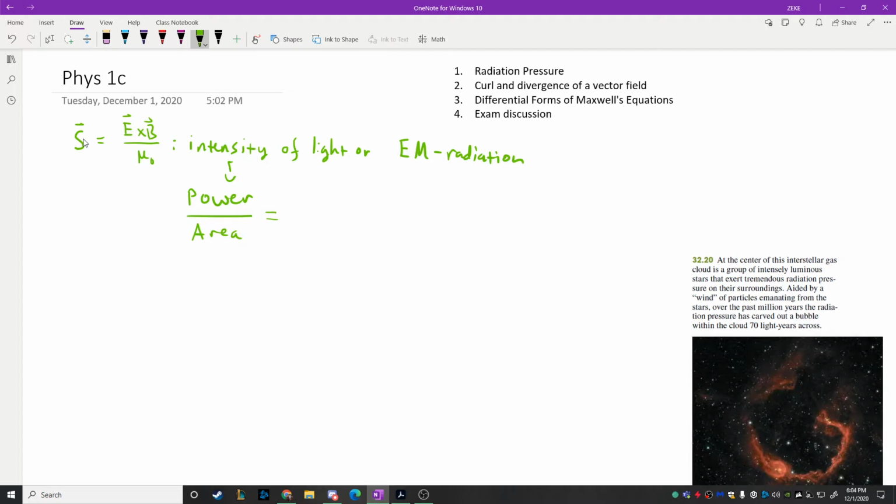For example, if you have a car traveling along a road at constant speed, you can describe the power output of the engine by figuring out the size of the drag force acting on the car, and then the force the engine needs to maintain to overcome that loss. It ends up being related to the velocity, because the faster you travel, the more force the engine needs to provide to keep it moving at that velocity.